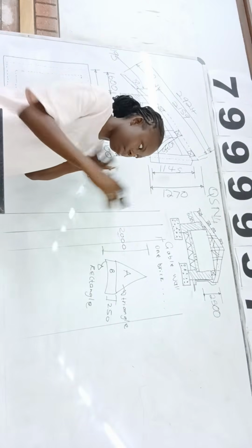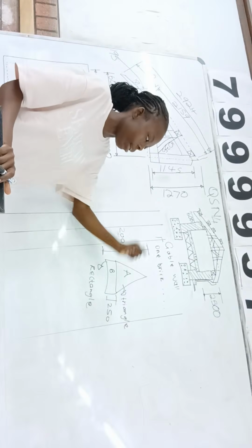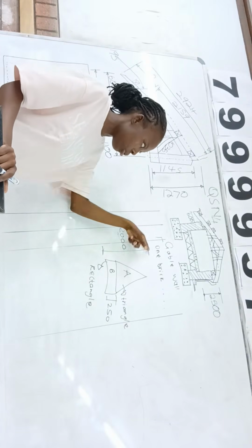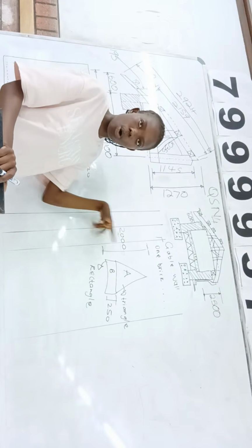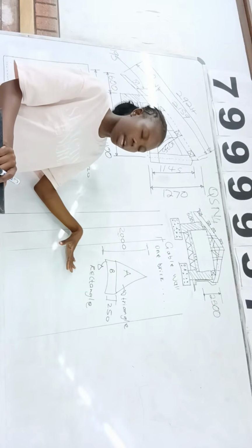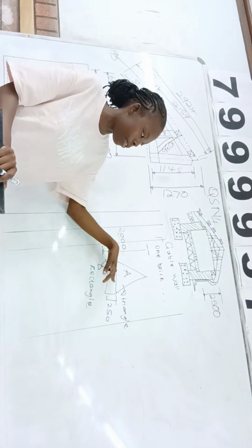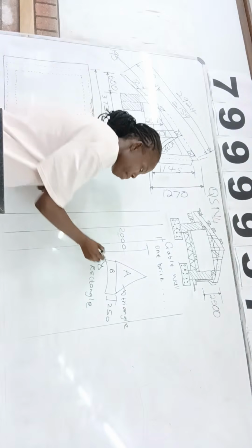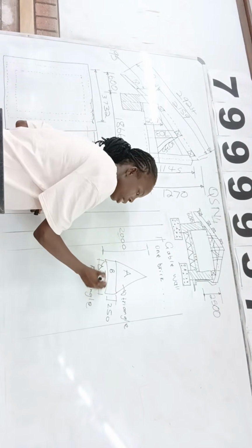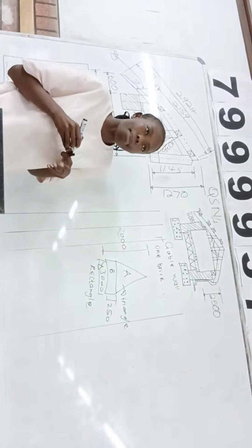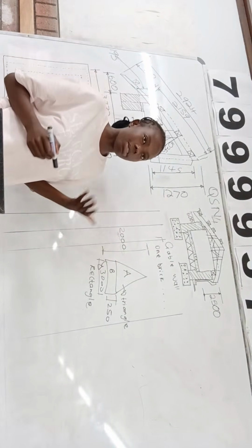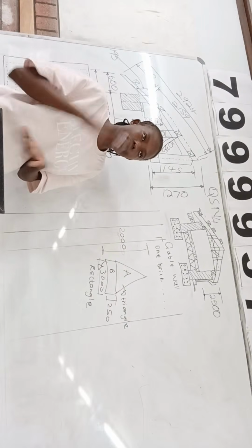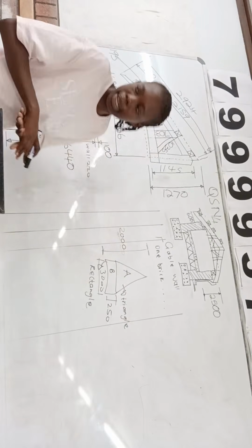You need to calculate them separately. So triangle. If you wanted the height of the triangle, you will take 2000. 2000 here is the height of the whole gable wall. Then you will subtract 250 for the rectangle, then you get the height for the triangle. But for the base, if the base of your rectangle is 3000, the base of your triangle will also be 3000. The triangle is sitting on top of the rectangle, so the width is the same.